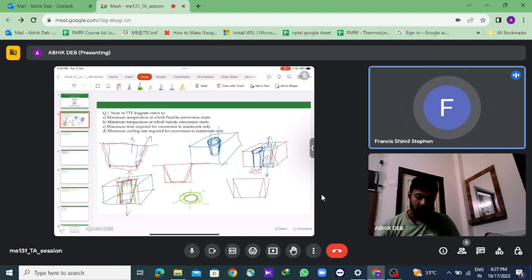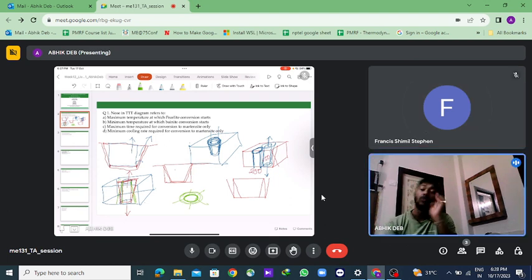That's what I'm saying, that first you will have to give the shrinkage allowance, then only you will give the taper allowance, because the taper allowance will be coming from the ultimate dimension. The taper allowance is related to the ultimate dimension of the object, irrespective of whatever allowance you are giving or not. So first you will give the shrinkage allowance, and then the taper allowance.